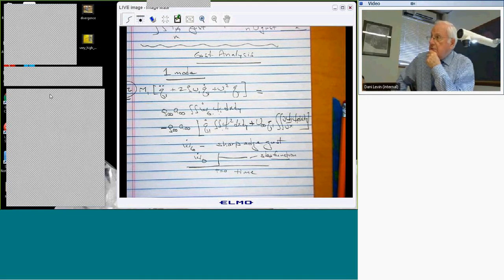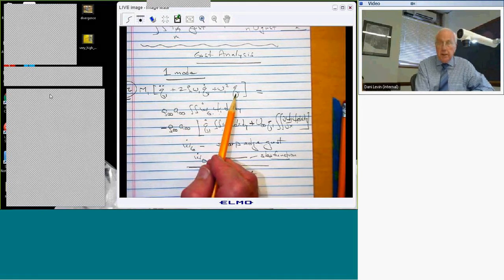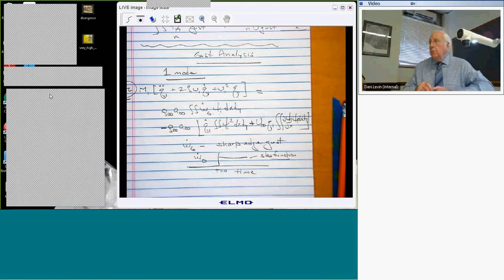You get oscillations. Do they damp out? Yeah, they damp out. And then what happens at very large time? Well, if things damp out, this term goes away and this term goes away, and I get a Q1. But Q1 just means I've displaced the airplane, right? It's just a static solution at large time. And what bothers people's stomachs and might possibly be an issue in terms of fatigue for the structure is the oscillations. Right? So the long time static displacement is usually not the primary concern.